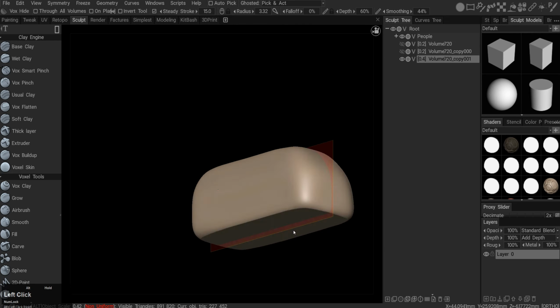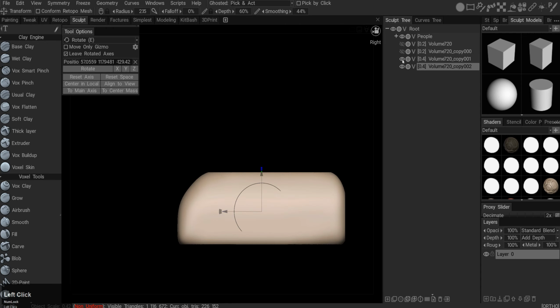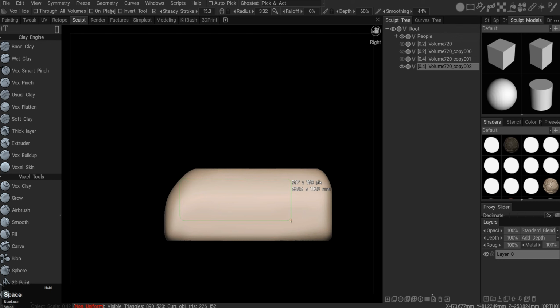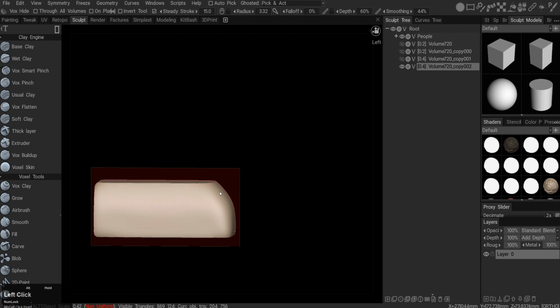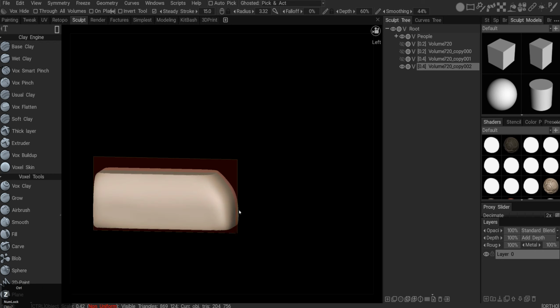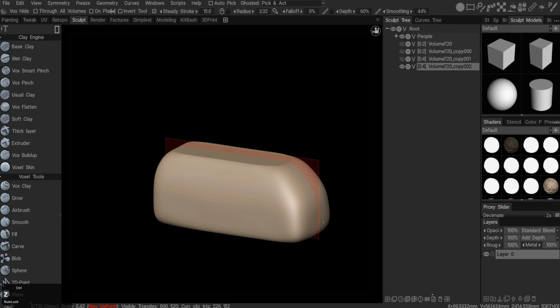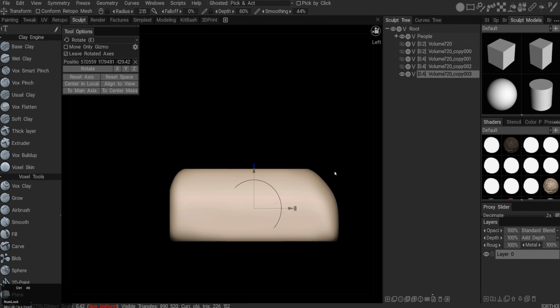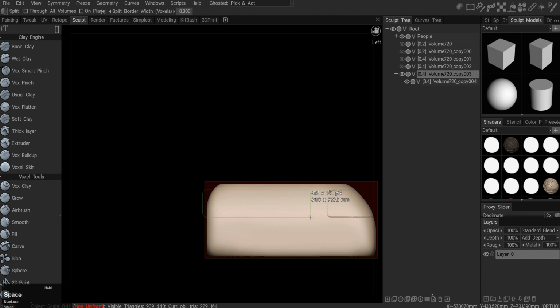So here I can see I built that cube and I smoothed it multiple times. It was at a low poly count, so I was able to smooth it pretty quickly. And now I'm trying to cut it with the cut tool, with the hide tool, and see if I can shape it a bit better. I'm cutting, then I'm using the voxel hide, hiding stuff, unhiding. And now I'm using the split tool to do the windows.